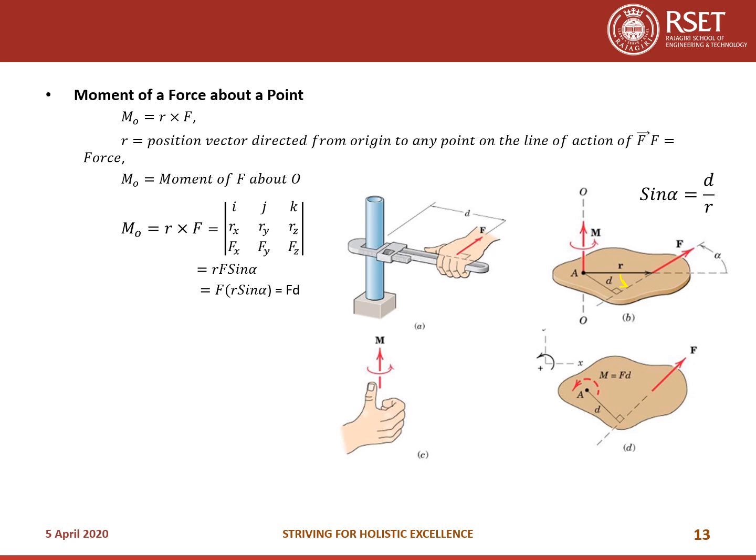So it is basically nothing but force multiplied by the perpendicular distance, the same thing we did in the scalar approach. And now see the way the moment is acting: it is anti-clockwise with respect to the axis of the pipe, which is OO, right? Take your right-hand thumb rule: the four fingers show the direction of the moment, and the thumb shows the direction of the moment vector. So if it is an anti-clockwise moment, the moment vector is acting up. That is the direction of the vector. That is how we can find the moment of the force about a point O.